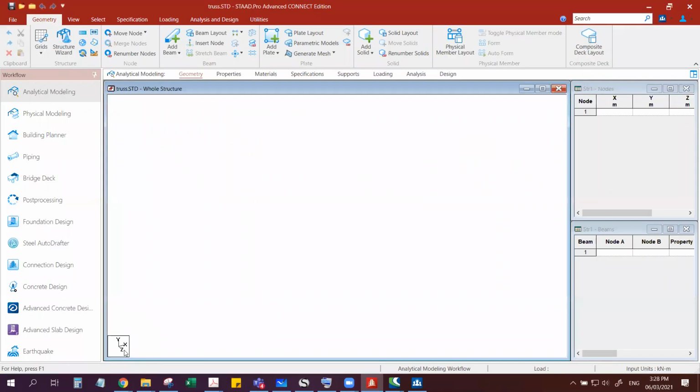Okay, so this is the global axis. That's why I'm saying when I'm training in STAAD, as a structural engineer, you should be now familiar with the terminology global and local. As you see in our derivation of the stiffness matrix, we refer first to the local axis, right? And in the second lecture, we now define the stiffness matrix of the bar in a global and an arbitrary orientation, assuming it's in a global axis.